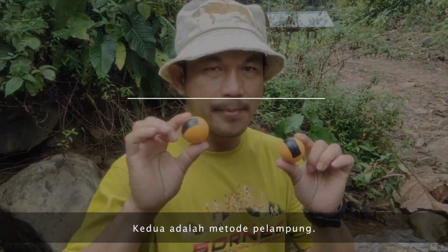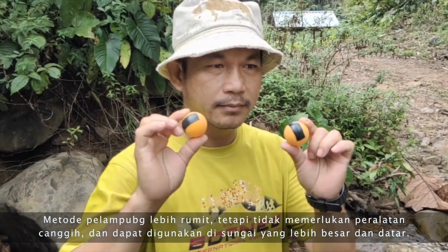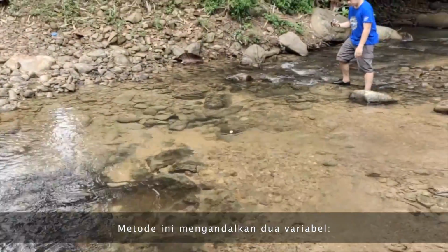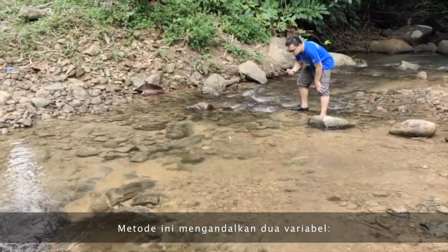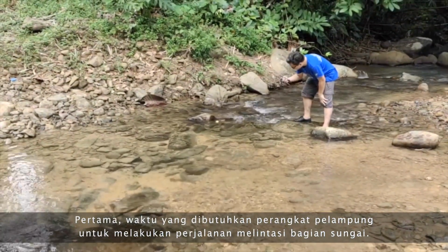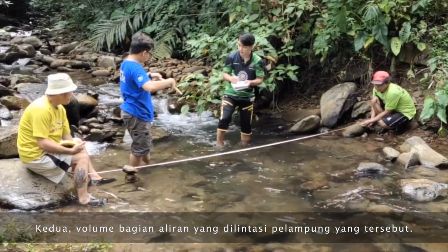Second, the float method. The float method is slightly more complicated but does not require any advanced tools or equipment and can be used in larger and flatter rivers. This method relies on 2 variables. First, the time it will take for a flotation device to travel across a section of the stream. Second, the volume of the section of stream that the float is traveling across.